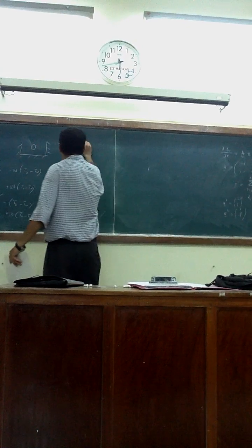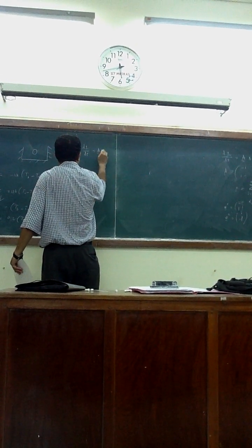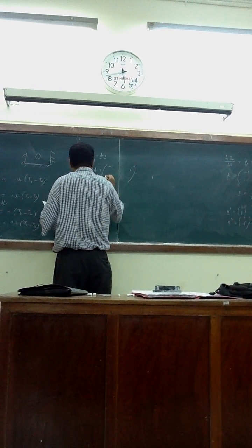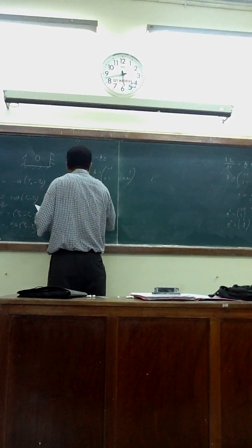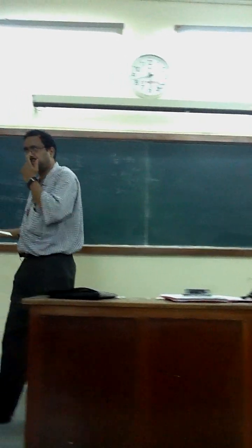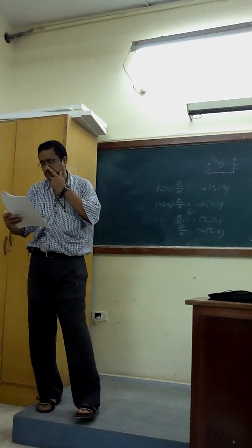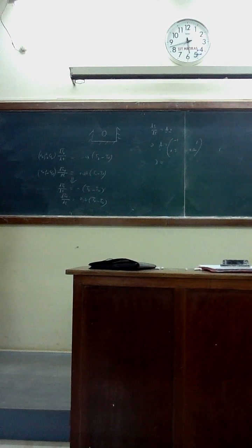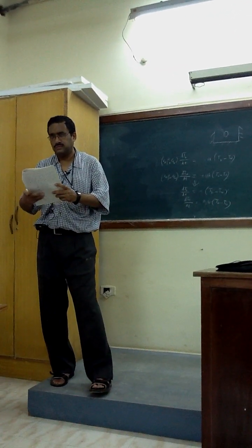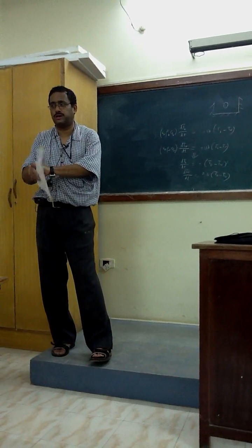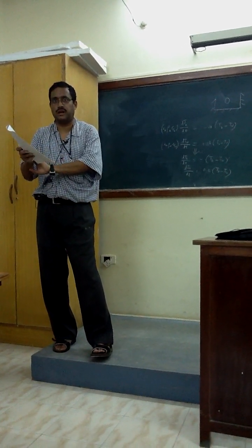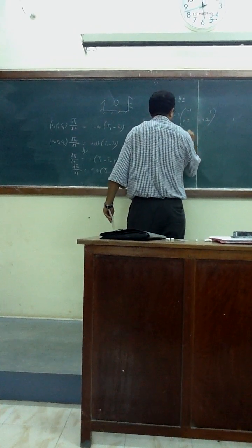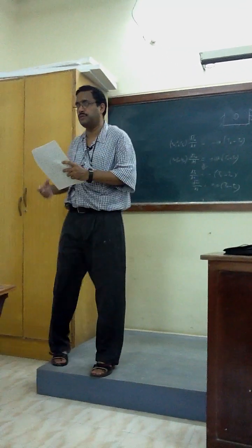So what is the A matrix then? If you try to formulate dx/dt equals Ax, what is the A matrix? Minus 1, 1, 0.2, minus 1. And lambdas will be? 0 is there, definitely, we know that without 0 you cannot get the correct answer. Another eigenvalue you need, otherwise you cannot get the eigenvector. Minus 1.2. 0 and minus 1.2. If you got plus 1.2, you get the wrong answer, because equilibrium cannot be achieved.